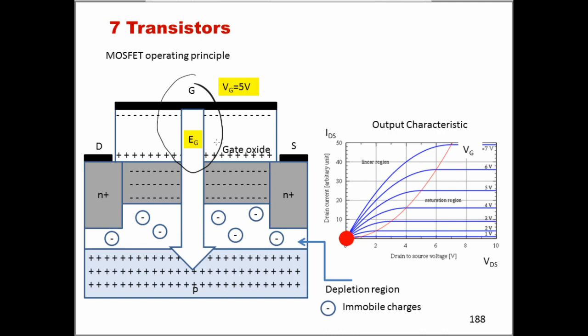Effectively, what we are doing is we are bringing this MOS device, which is made of a metal, an oxide, and a semiconductor here, in inversion. We are attracting minority carriers. This is a p-type silicon substrate, and so we are attracting electrons that are minority carriers to the interface. So we are bringing the MOS stack in inversion.